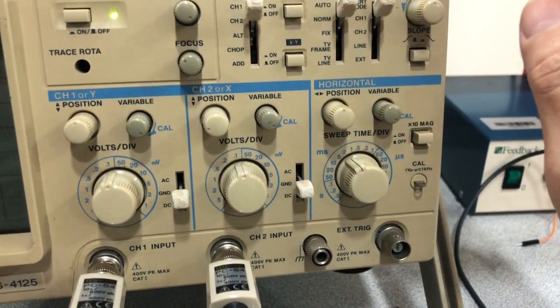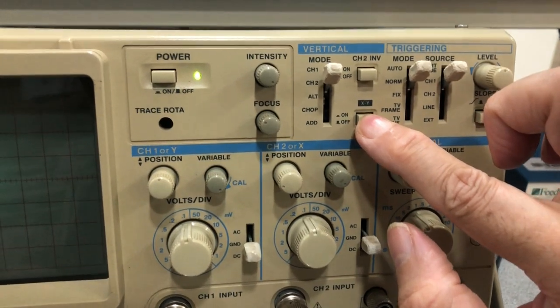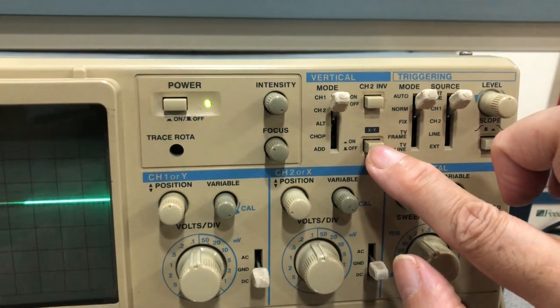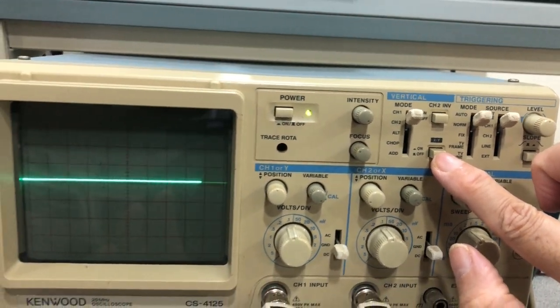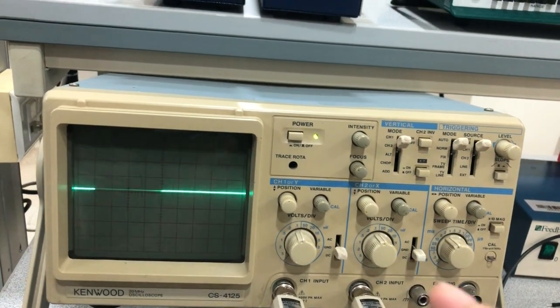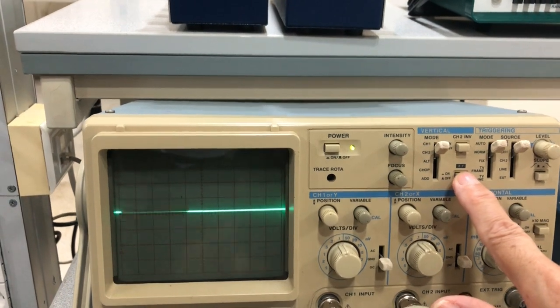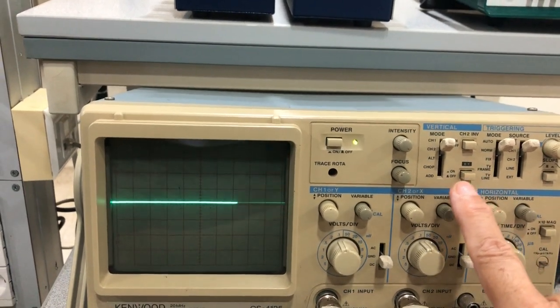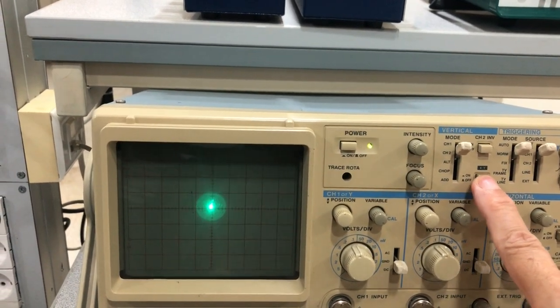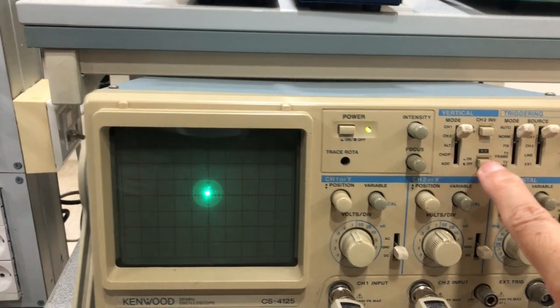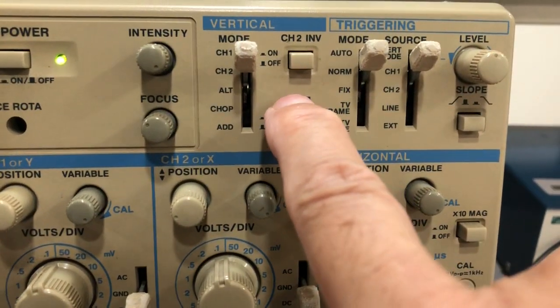So why is it stuck? I think we are in some XY mode. This is a button called XY mode. It's an advanced mode. We plot voltage versus voltage, like V versus I for the diode characteristic. So when I saw a dot, I remembered from long experience that I am in the XY mode. So this button was pushed in, on, and I am in XY mode.